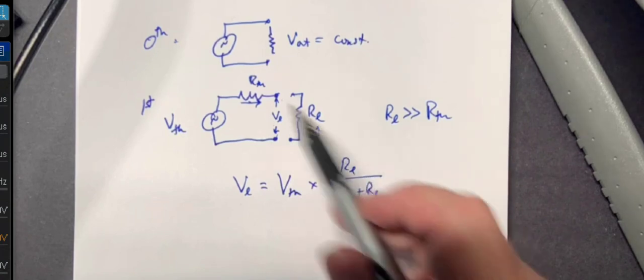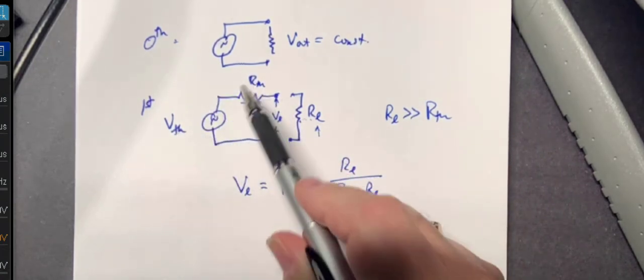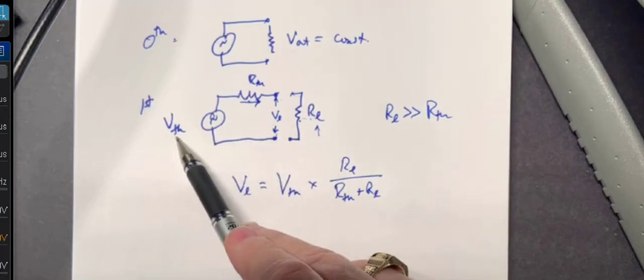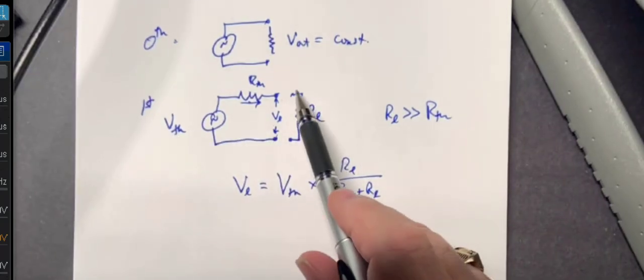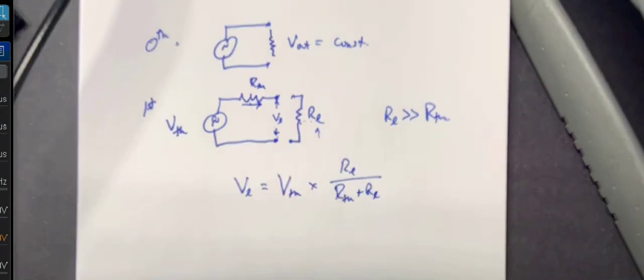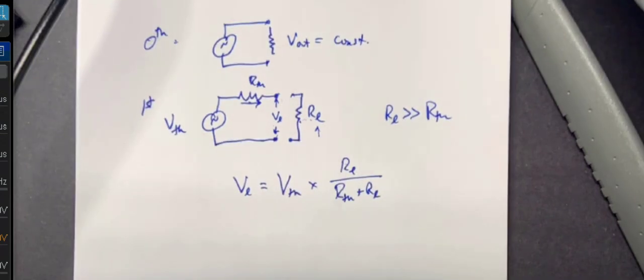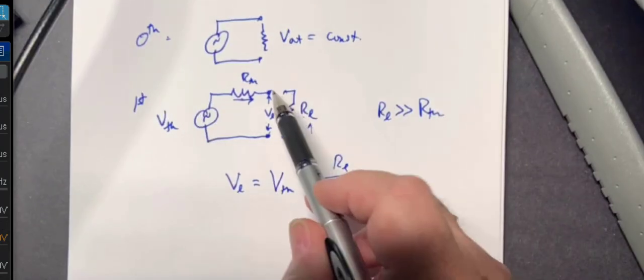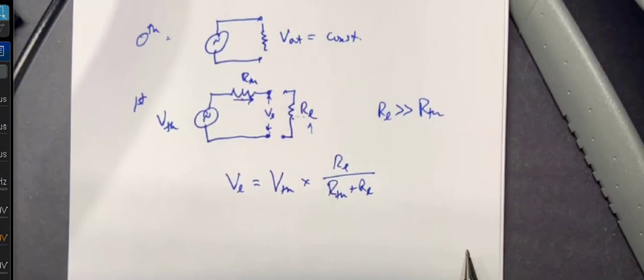How do we get these two values that fully characterize our source? Well, how do we get the Thevenin voltage? Really easy. We make the load resistor really high. And that's what we've done when we did the measurements with the scope set for 1 meg input. When this is 1 meg, it's effectively open, and the voltage we measure is the Thevenin voltage.